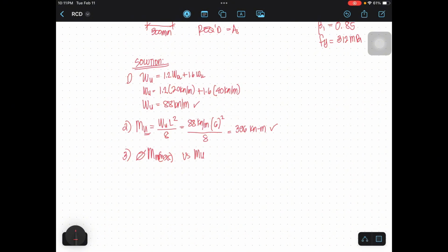Okay, so for the maximum moment, we have a formula, reduction factor 51 over 140 beta 1 f prime c bd squared quantity 1 minus 3 over 14 of beta 1.